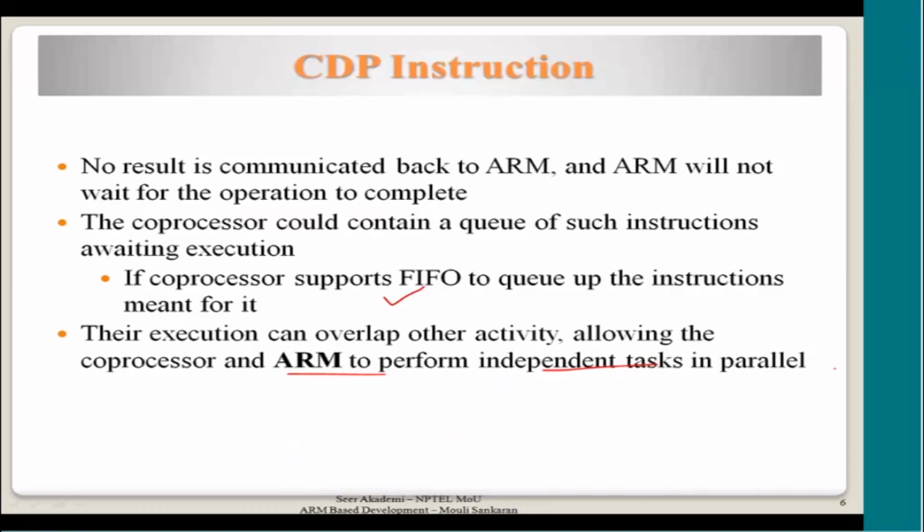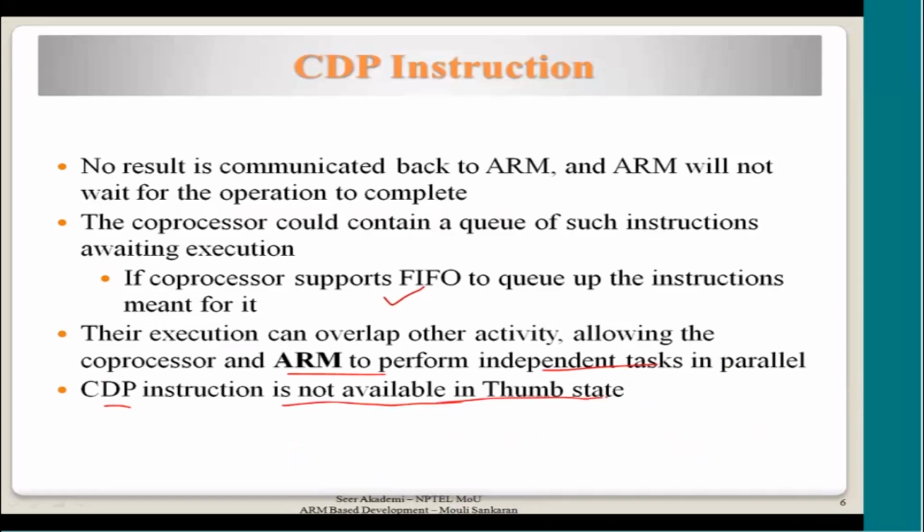If ARM and coprocessor are not running in parallel, then we are not having the benefit of designing a hardware specifically for processing the coprocessor instructions. CDP instructions are not available in thumb state. See, any coprocessor instruction is not available in thumb state for that matter, but I am making a statement clearly saying that these are not available in thumb state.